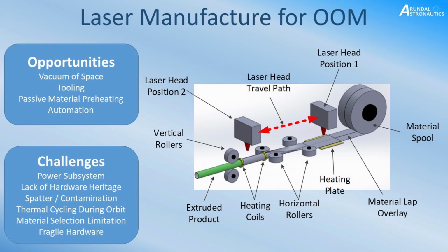A simple top-level explanation of why a vacuum helps with laser welding, especially keyhole welding, is that the plasma formation that we discussed in the previous slides is suppressed in a vacuum. Because less of a plasma field and plasma cloud is formed, more of the laser energy can reach the workpiece and therefore heat the material and continue with the welding process.